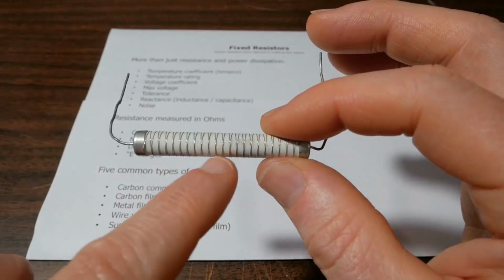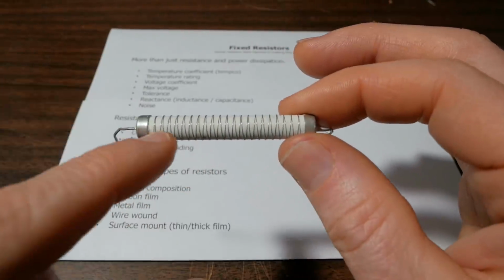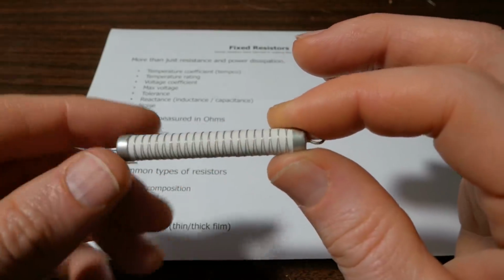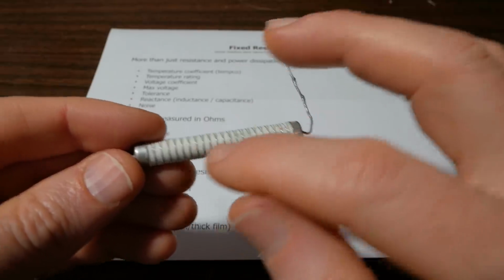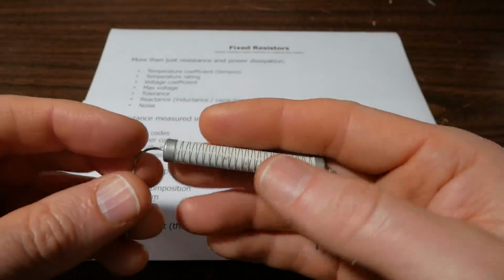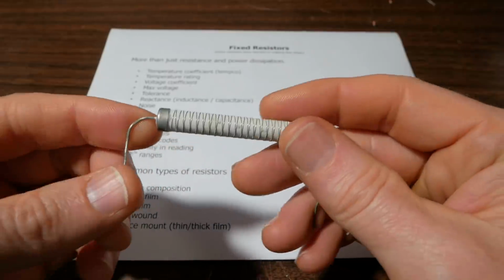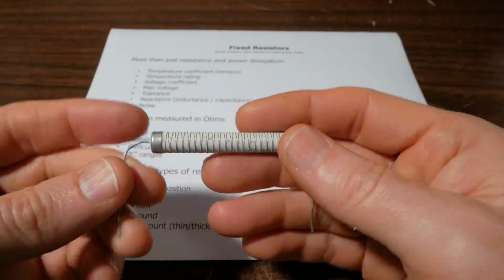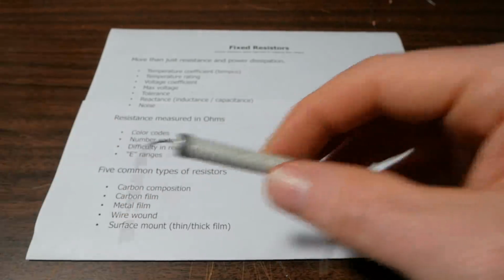You might say, well, don't they short at the crossover points? Well, because the coil is equally spaced, equal length, and same type of wire, these are equal potential points, so it doesn't matter. So you end up with a very low inductance, and I really hated to bust open my low inductance 20 watt power resistor here, but it's pretty interesting to see this type of winding in use.